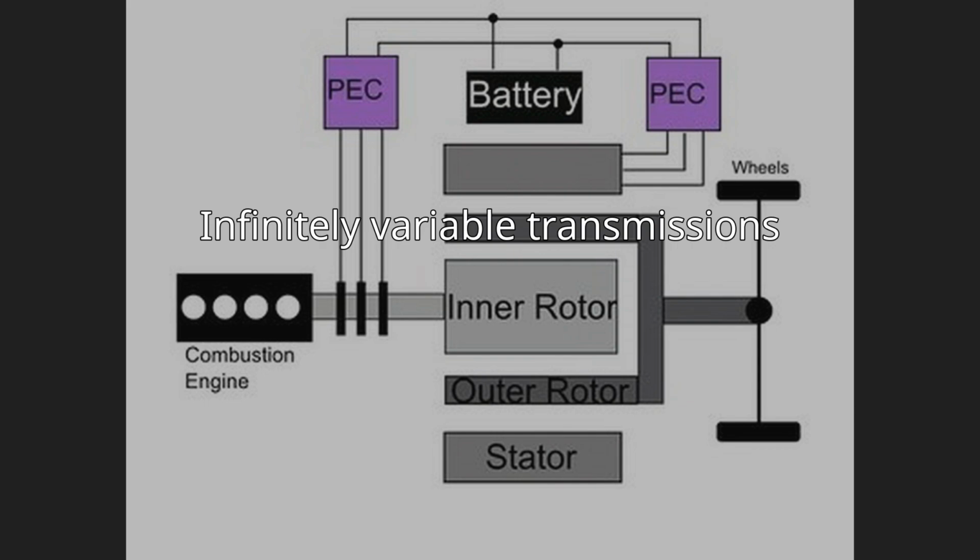Infinitely variable transmissions. Some CVT can also function as an infinitely variable transmission, IVT, which offers an infinite range of low gears, e.g., moving a vehicle forward at an infinitely slow speed. In an epicyclic IVT, infinitely low drive ratios are produced when the output shaft rotation speed is equal to the difference between two other speeds within the CVT. In this situation, the CVT is functioning as a regulator of the rotation speed of any one of the three rotators of the planetary gear system.